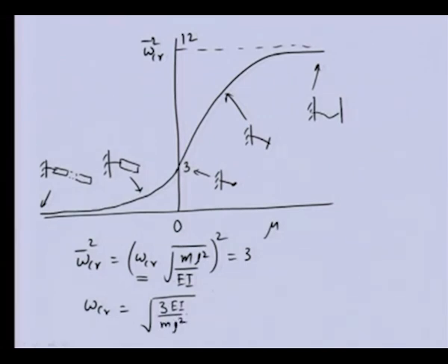And if you see the stiffness of the cantilever beam for point mass, it is basically EI by L. So, basically this represents K by M for point mass. For this particular case, we got the value of 12. So, if we use it here, we will get the critical speed.